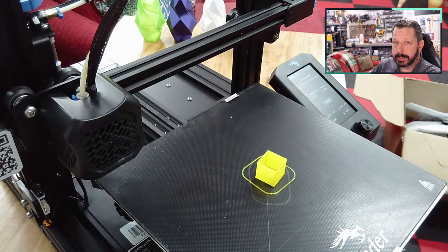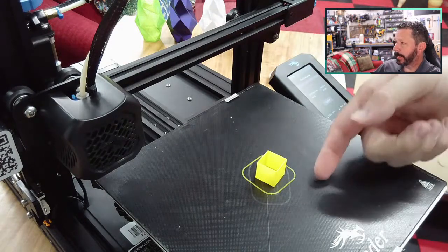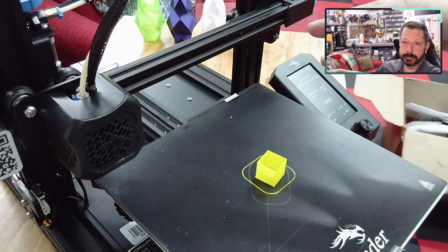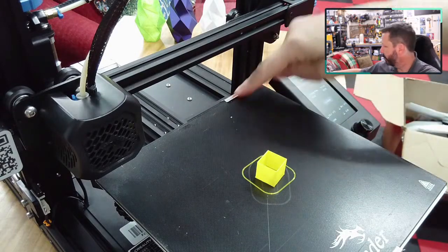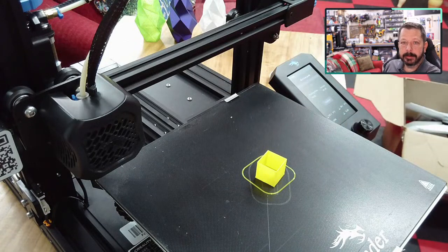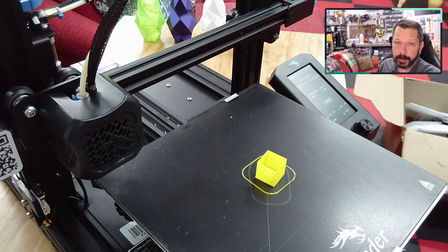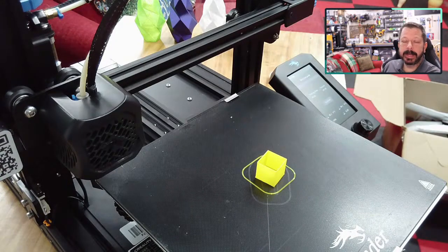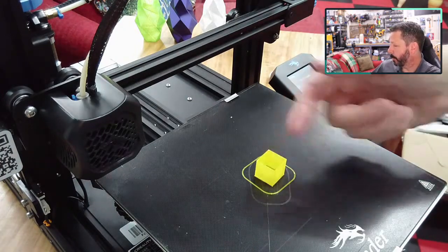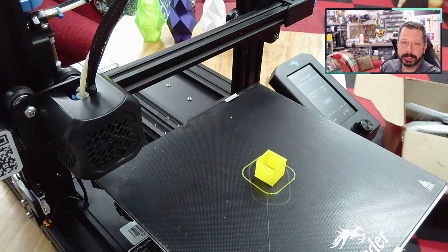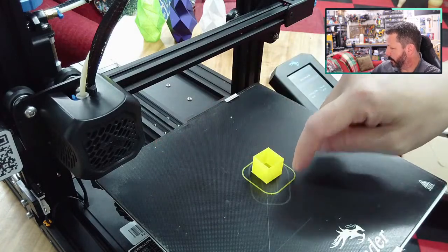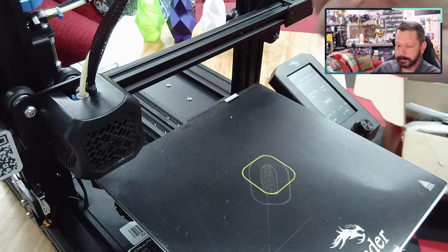So if that happens, what you do is, instead of breaking or scratching up your surface, take your surface off, assuming your surface is removable. So most of them are. They either are magnetic or they have little clips or whatever. Let that surface cool a little bit, and then put it in the freezer, like the cold part of your freezer, for 5 or 10 minutes, and the part should pop off then. Because you get differential cooling between the part and the plate, and it'll pop itself off of there. But it should be that you've got your print nozzle just the right height from the bed, where you can just peel it off, and it's really easy.